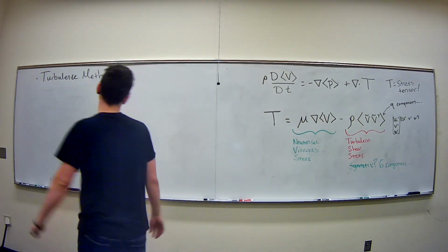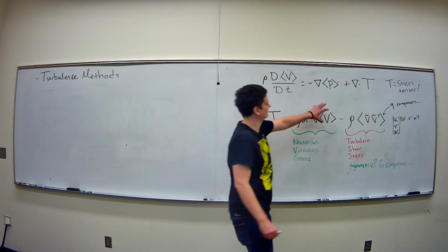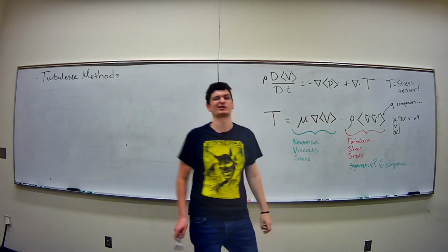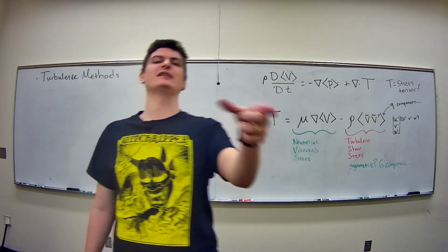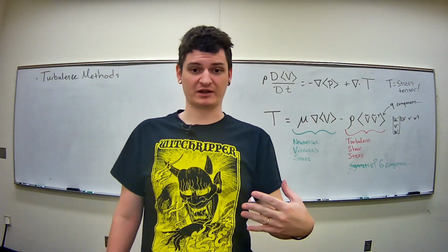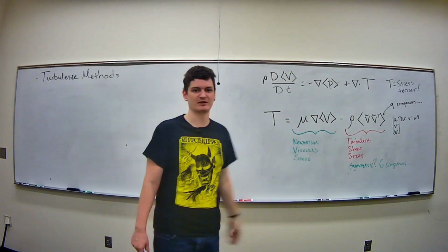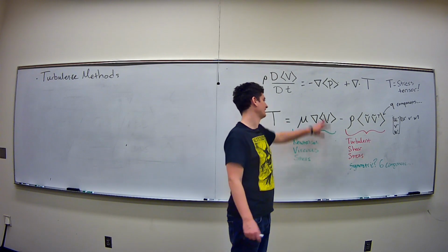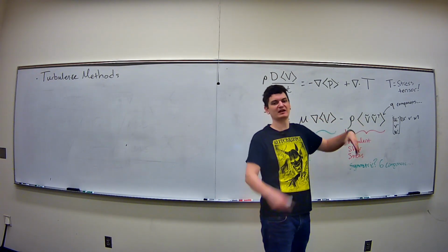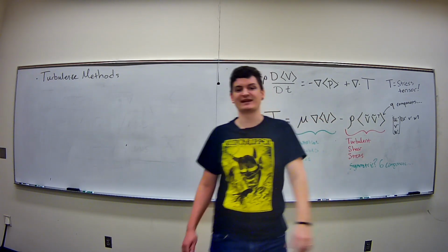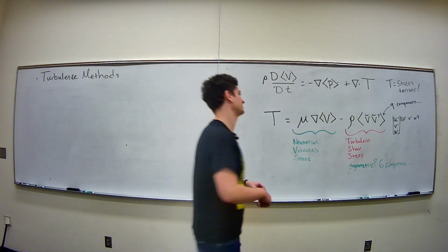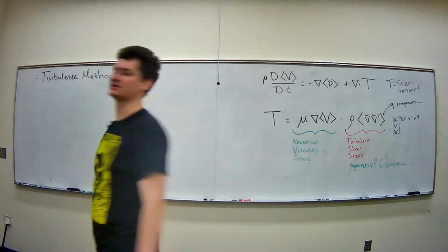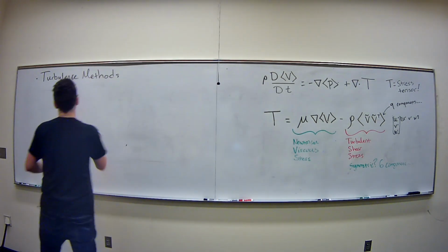Okay? And this is then certainly the closure problem we arrive at. If I want to model, we start off by saying, how in the heck does my mean flow evolve? It looks like a good quantity to model in fluid flow that's turbulent because I get wiggly lines, but I can take an average after my computer did stuff, right? I can take an average after my experiment and get that data, but I want to know a priori what does that look like if I'm evolving. Well, it turns out because of your assumption on the solution form, this idea that I have a mean plus these fluctuations, you don't know what the fluctuations are either. So you've added more unknowns than there are equations. So this is the closure problem.